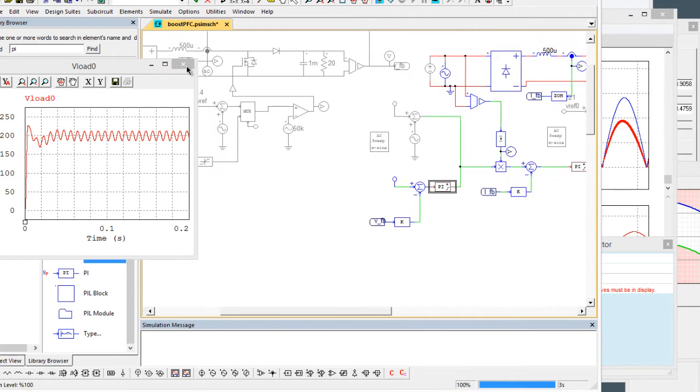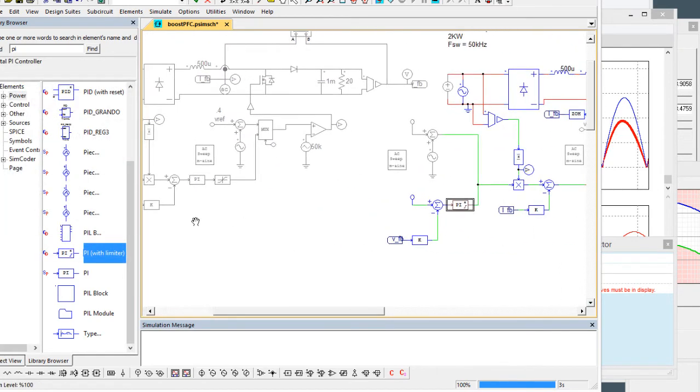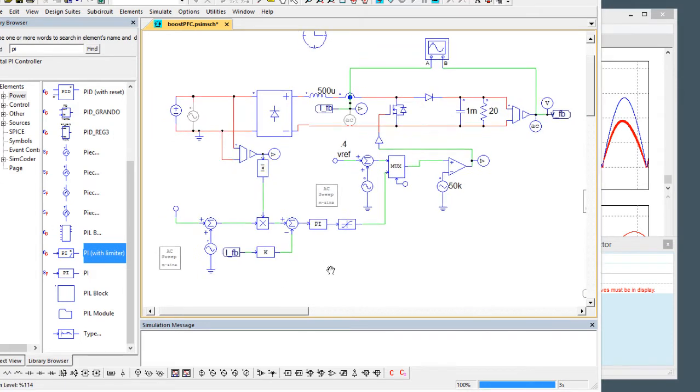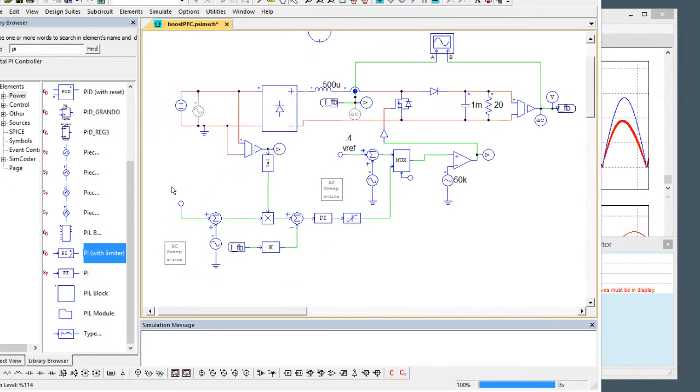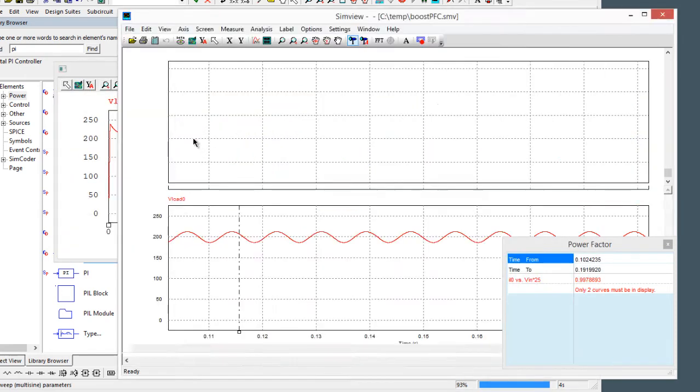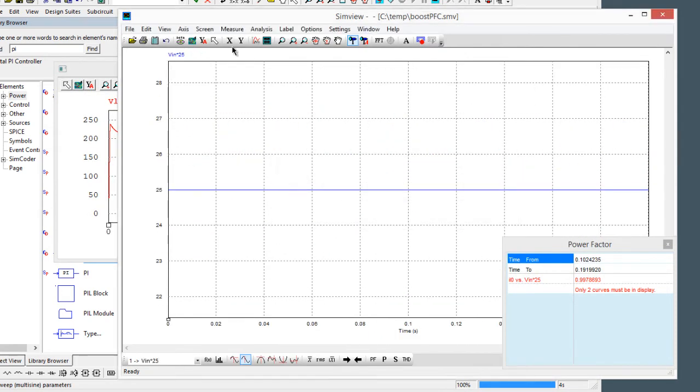Okay, so let's do the analog side of things. Same as the digital end of things, I've got this all set up now for our AC sweep of the output voltage. We've got our reference set up. We're running in DC. This is pretty key over here still. We've got the AC probe set up on the output voltage, and again, it's a gain of 1 there. So we need to run it in DC to see when steady state is, and it looks like 100 milliseconds again is going to be a good look at that.